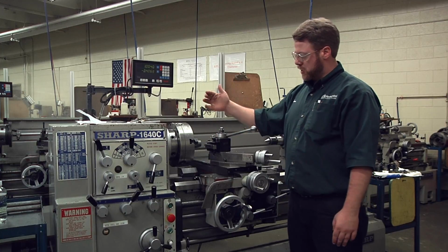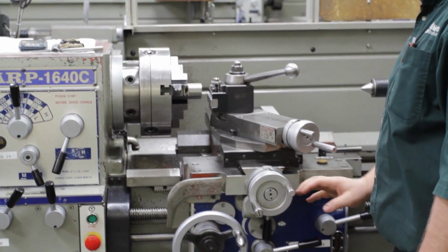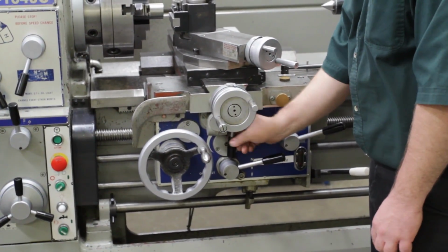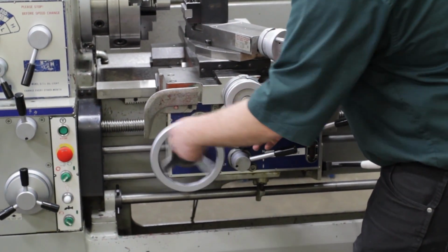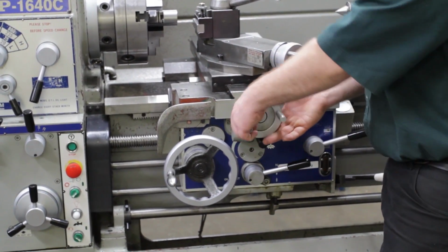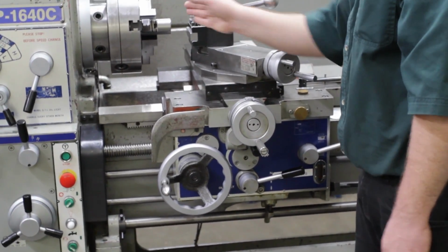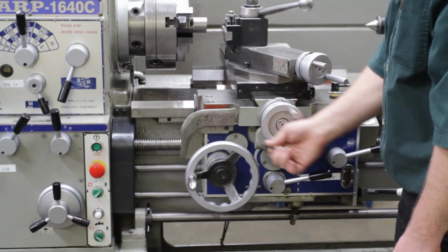So what I do there is I'm going to start up the machine. I'll have to set the carriage for facing. Remember, this handle changes the feed direction. If this handle is down, it'll control this handle. If this lever is up, it controls this handle. For a facing operation, you're simply cutting off the end of the shaft. So you're going to use the power feed in this direction.